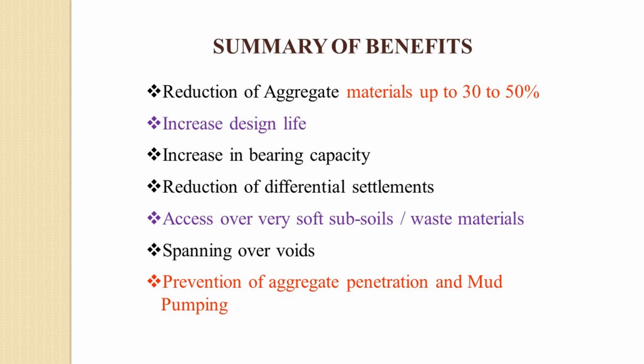That is a material, a grid or a textile or a grid and textile, which can withstand the inlet temperature of more than 160 degrees, which has very high strength and very stiff grids. These materials are used in the asphaltic layer as asphaltic reinforcement. Normally a crack appears, we go and redo the surfacing, and after some time the crack reappears. This is arrested; this is called asphaltic reinforcement.